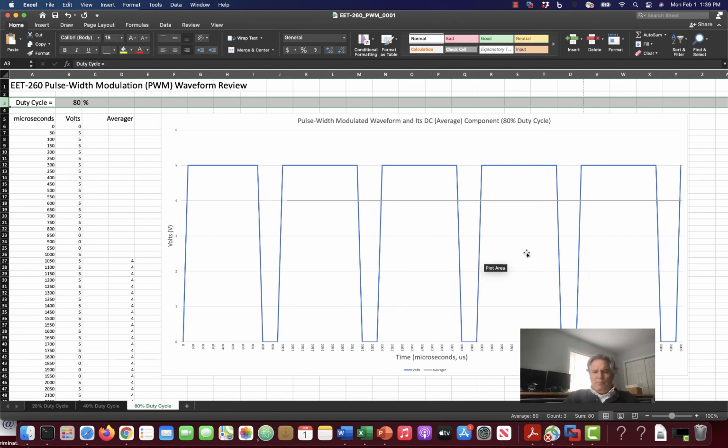You truly transform the power from one configuration, the voltage and current, to another configuration that's regulated where you want it. And those systems, like some of the motor control systems, have feedback to say, I want 3.3 volts. You're now a whisker high. Maybe you should make your pulse width a little bit shorter. Or I'm at 3.3 volts and I'm just a little bit low.